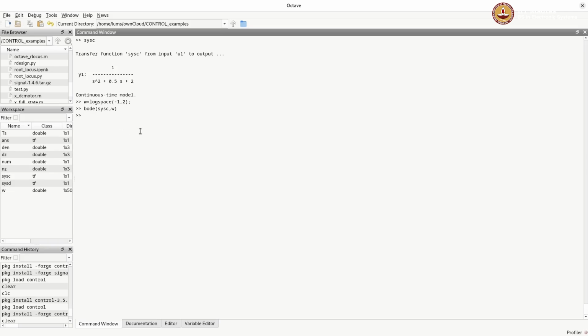Important thing is that the variables are vector based. So just like you have the integer numbers and real numbers in most programming languages, in Octave and MATLAB, a 1-by-1 vector element is the basic building block. Use that concept effectively and you will be able to get very efficient and nice scripts.